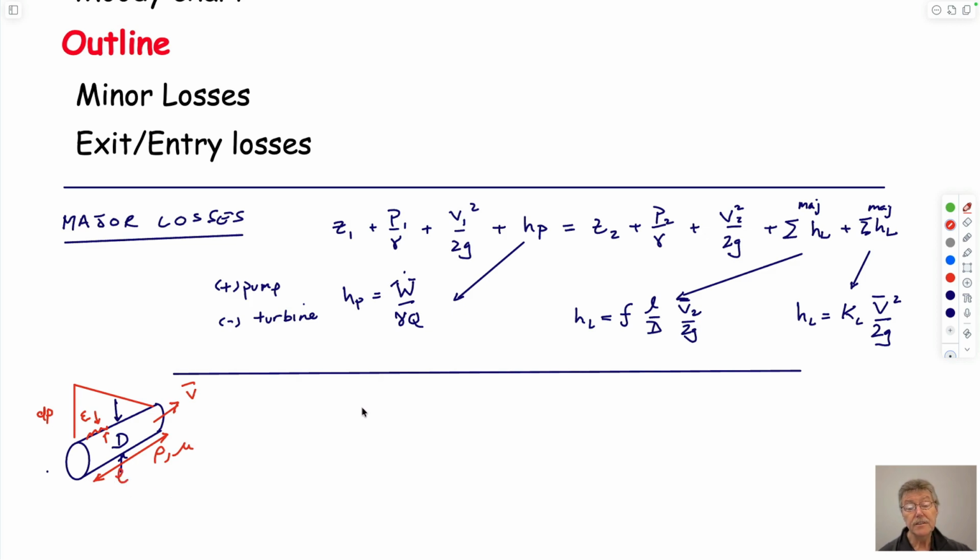That's L. And so you might remember that if you solve the Navier-Stokes equations for this, which came from the momentum equation, with viscosity added for losses, which we didn't dwell on too much, we ended up with a solution where the average velocity across the pipe is equal to the pipe diameter squared over 32 times the viscosity, and the pressure drop, delta p over the length.